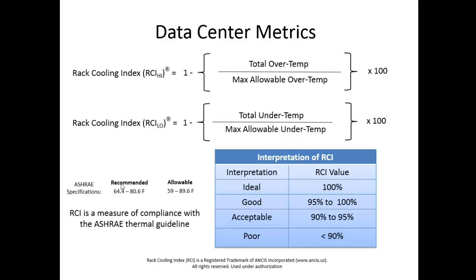In fact, many will argue you want to run 77 degrees or lower because the fans inside these servers are becoming multi-speed, and they generally trigger to a higher flow rate at around 77 degrees. So you certainly don't want to be higher than 80, or you begin to defeat the purpose of reducing the supply air.